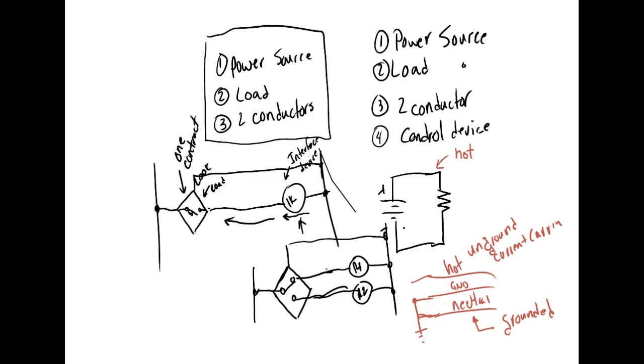Normally we want to use the one that is normally open, because the temperature level set will cause it to energize. The one that is called reset is de-energized. So this one would operate opposite of the way we want it to work. This one right here would operate directly. So as soon as you apply power, whichever relay energizes is not the one you want to use.